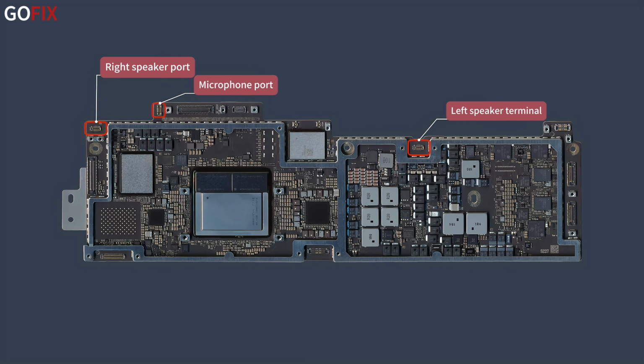In daily laptop repairs, over 75% of faults are power-related. Now, let's explain the various power-related parts. This model is equipped with 2 USB-C ports and 1 magnetic connector charging port. Both USB-C ports support Thunderbolt 3 and USB 4 protocols, and both can be used for charging. Their circuit principles are basically the same, and they are independent.